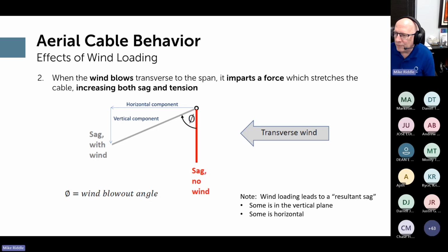It has a pronounced fatigue limit that's much lower than steel. So normal sag and tension changes, just from environmental effects, the daily expansion and contraction due to temperature changes, and for now I'll call it moderate changes in wind conditions, you're not likely to fail a cable from anything like that.